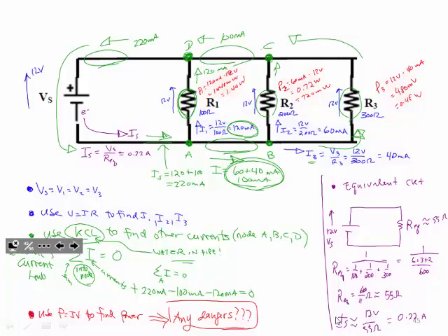I'm going to turn on my power supply. So we're a little bit high on my voltage. I'll bring it down a bit. So there I am around 12 volts. And my current is 0.22, 220 milliamps. It works. Now, let's measure the current in a second spot here.